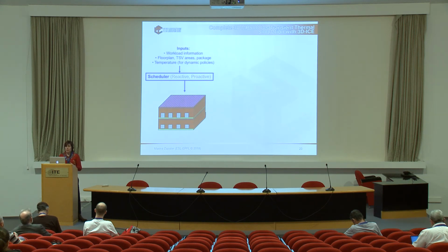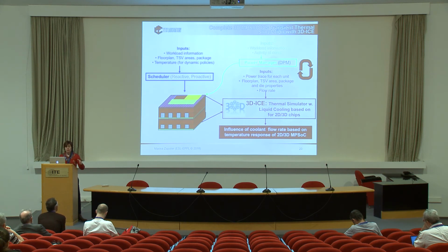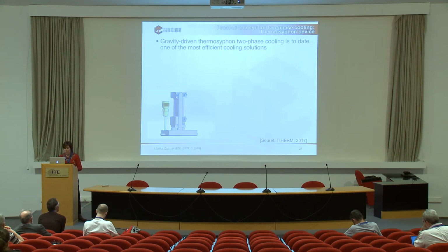Okay. So just to give you a hint of what else we can do, 3D-ICE can be integrated. We proposed a methodology on how to integrate 3D-ICE into complete flows for MPSoC thermal simulation. You can even integrate it with the schedulers, because you can make 3D-ICE run in a loop, and you can test different power management policies with 3D-ICE to understand how your chip is behaving during runtime, and see the influence of your workloads on the system and on the thermal profile.